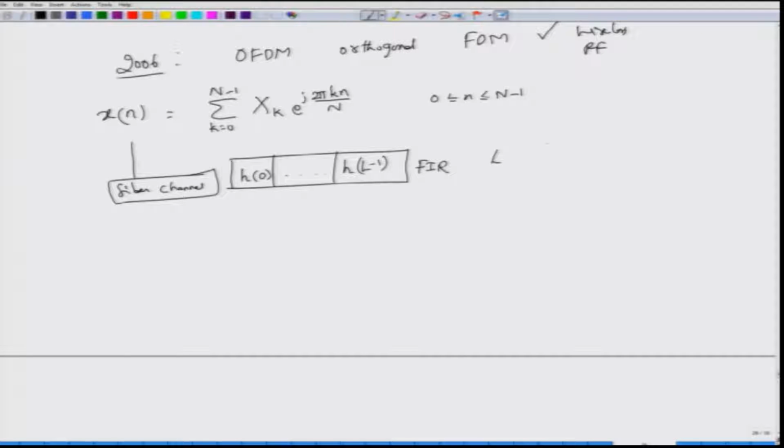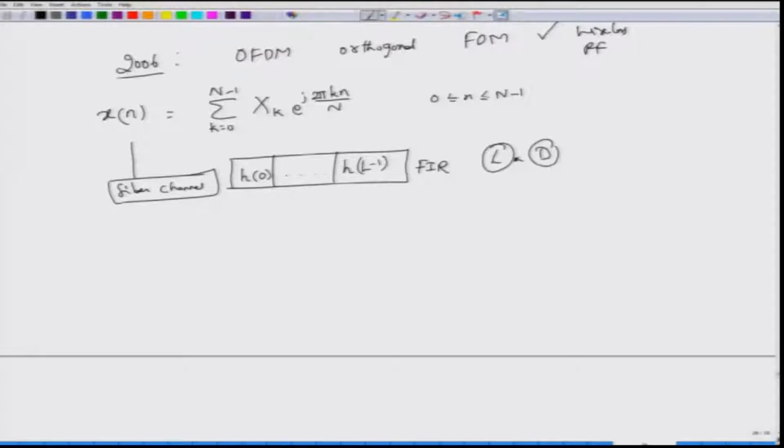The length here actually depends on the dispersion coefficient, and it has to be chosen in a certain relationship between L and D. We are not going to look at this relationship, but I will develop it in the problem sheet that I will give you, okay. So, for now let us assume simply that this L is large, but it is not really infinite, okay. If L is really large, then you will have to wait until the samples arrive at the output, and this delay will be quite large. So, it is not too large, but it is not too small either, and whatever the length L is, it is determined by the dispersion of the fiber, okay. So, the larger the dispersion in the fiber, the larger will be the value of L.